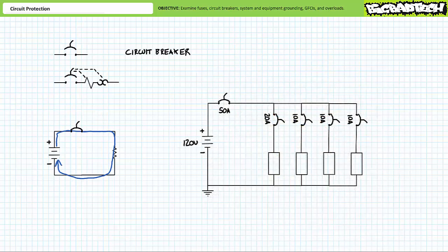Circuit breakers often work in coordination with other circuit breakers in a larger electrical distribution system. We'll explore parallel circuit properties in later lectures. However, consider this simplified explanation. Consider a 120 volt source with a single master circuit breaker rated to open at 50 amps, which feeds several other circuit breakers of different ratings. Let's say a single 20 amp circuit breaker and 3 10 amp circuit breakers.